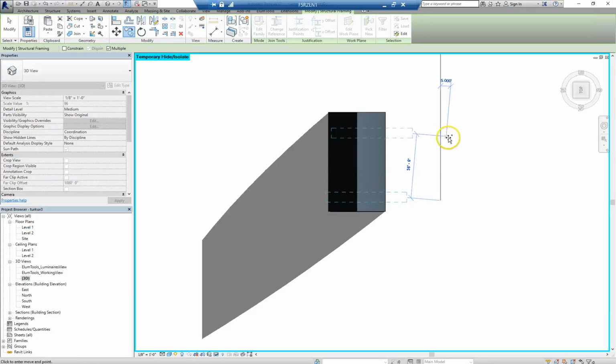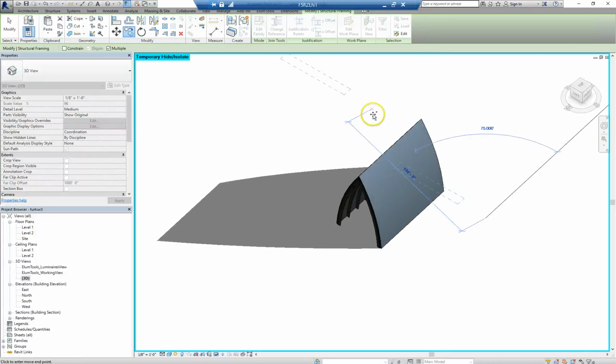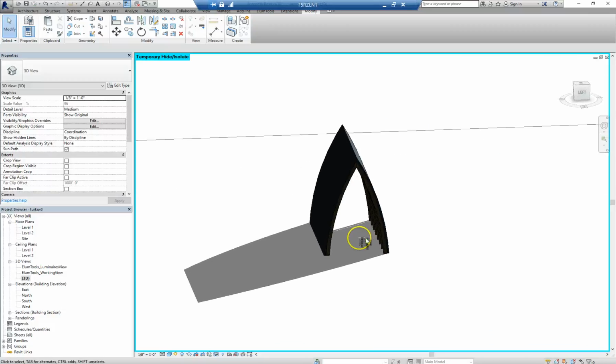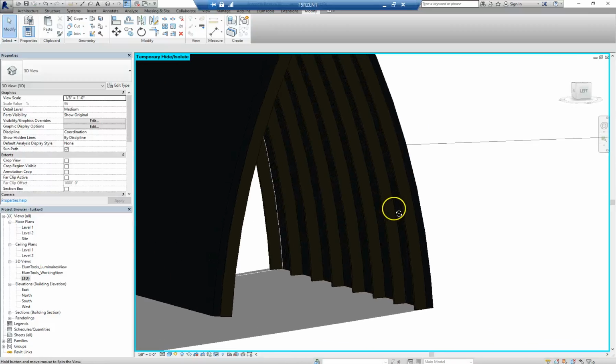And then keep going. Unlike some other programs, with Revit, whenever you move something 8 feet, it starts at 0 again for the next thing. So you don't have to do 8, 16, 24, 30. You don't have to do that. You could just do 8 feet, 8 feet, 8 feet, 8 feet. That way, they're all spaced. You can also use the array tool, but I just like copying things sometimes and not doing the array tool, which then groups them all together.